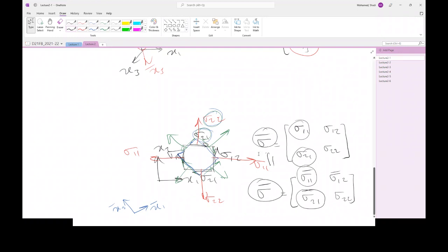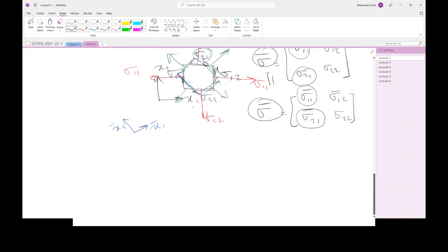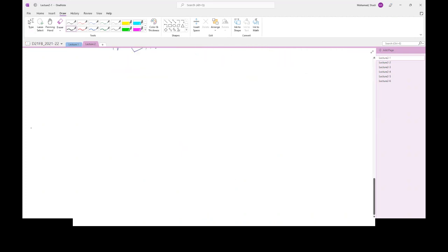All right, now this is the case in 2D. However, you can work exactly the same situation in 3D, and actually the stress would be most of the time active in 3D, unless we talk about the plane stress situation, which is an approximation of the reality. But if you move into 3 dimensions, you have x1, x2, and x3. In this case, the projection would happen on a cube. And you have probably seen this cube where you have the normal stresses, and then you have the shear stresses in one direction, the shear stresses in the second direction.